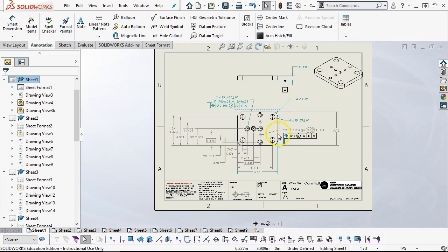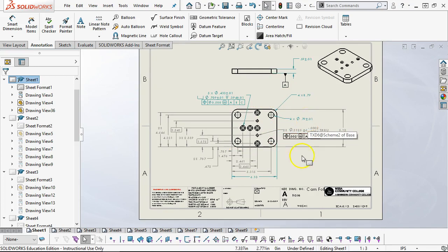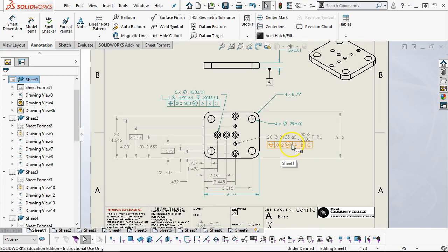All right, and then the outsides are not controlled radiuses. The diameter we talked about. And what I don't see then is a, oh yeah, we got the counterbore. All right, so we're all covered. All right, so on the other side of this, this drilled and reamed callout is selecting a pin. So if we go to a standard dowel pin or pick up a precision, probably a stainless steel 18-8, what else would it be, 3, anyway, one of the 3 series pins, that would also give us the shaft size and how much actual interference we could expect from the part.